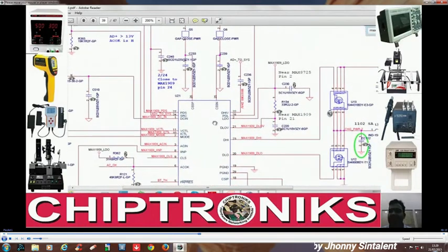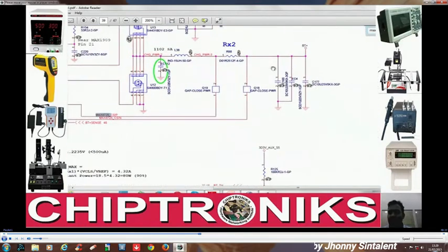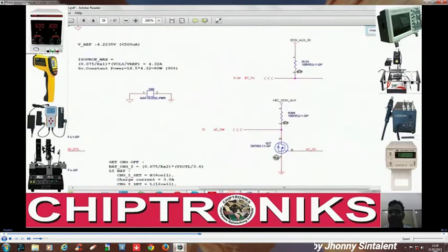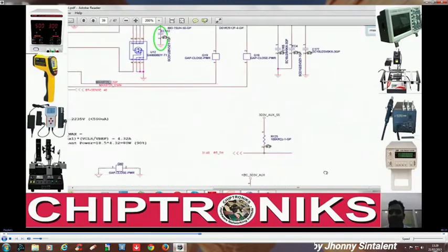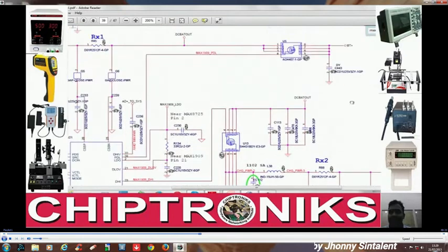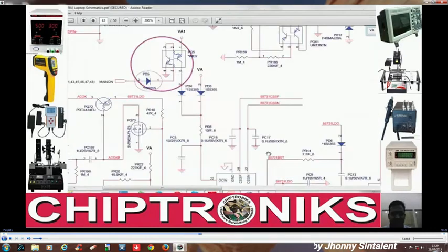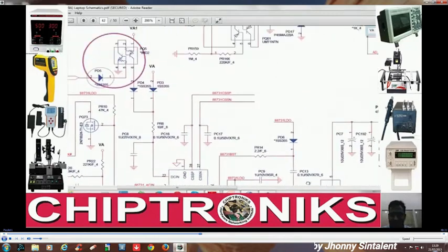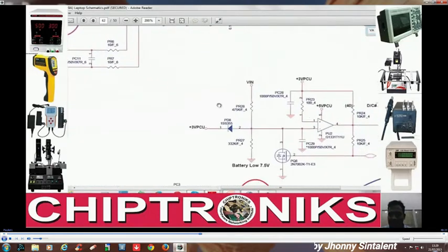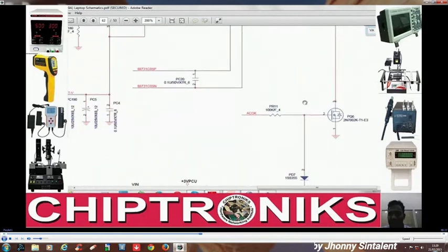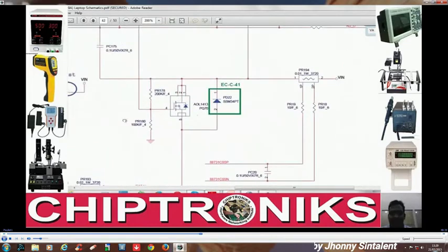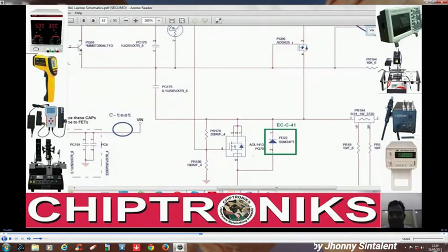And it will generate AC OK, but you will find over here that AC OK is not going anywhere to open a MOSFET, right? Here in the i3 case you will see over here the AC OK is basically going to open a MOSFET so that the VA becomes V in.